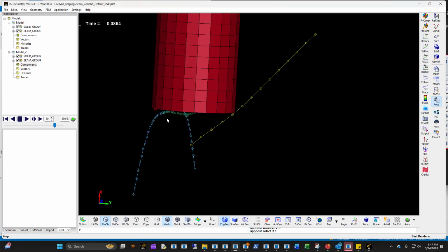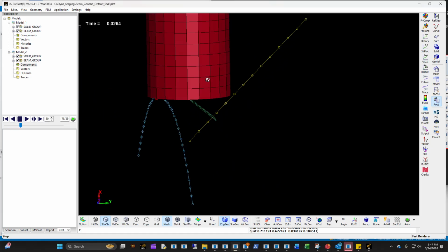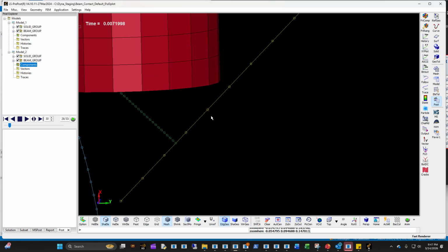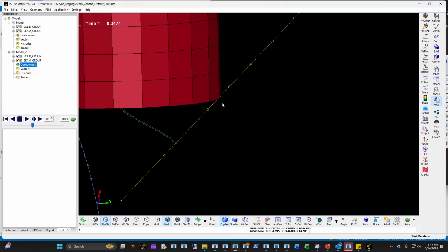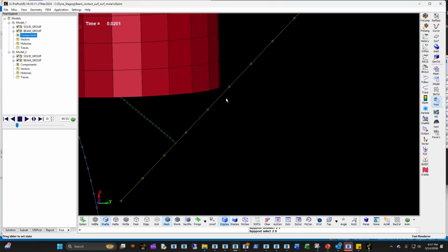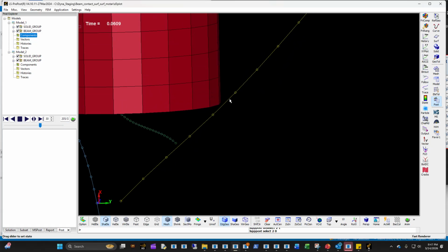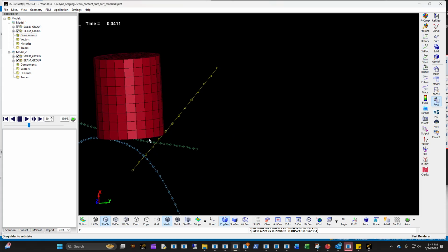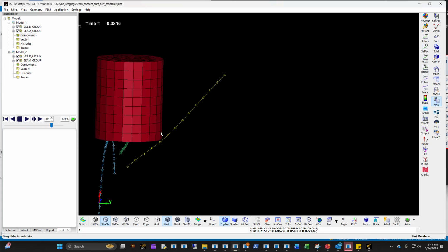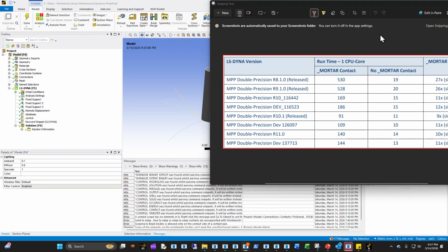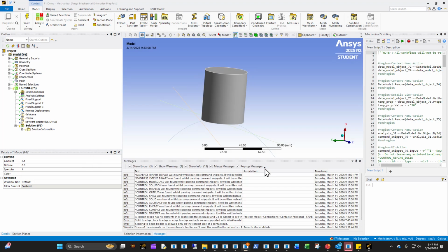Basically, it looks like this. And I will talk a little bit about how contact is generated, and how you can overcome things like this with a different type of contact formulation where you can allow the edge contact to occur, like right there. In some cases, we don't have that edge penetration, and that's really the kind of problem that we usually run into. And there's also the problem of having correct beam-to-beam contact and shell edge contact, which sometimes presents certain challenges that we want to be able to overcome. Okay, and we're going to do a problem like this today.